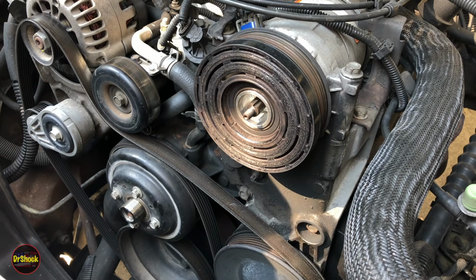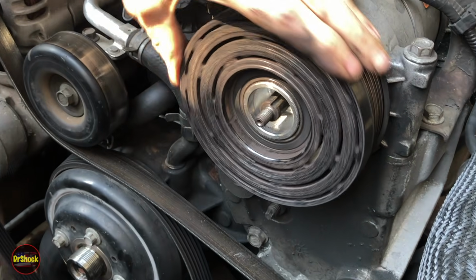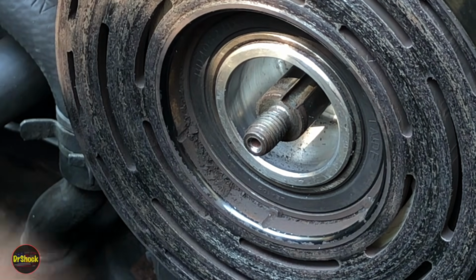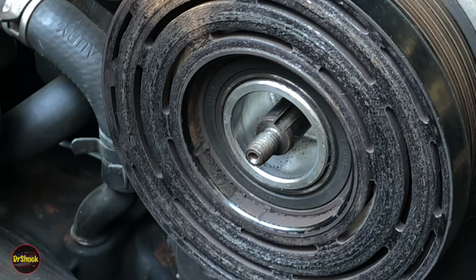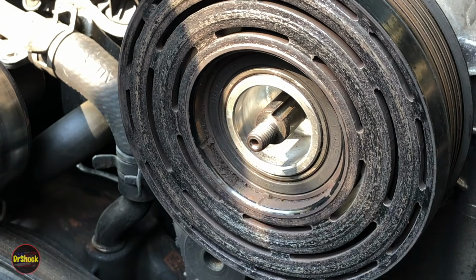I'm just going to stop here just for a second just to show you, this is all meant to be put on a press, and so we're putting it on the vehicle. You got to be careful that you do these short sideways blows like I'm doing, because you definitely don't want to damage the radiator. That's why I'm going very slow here.